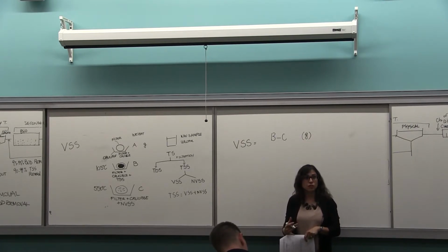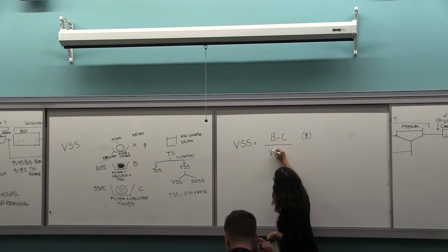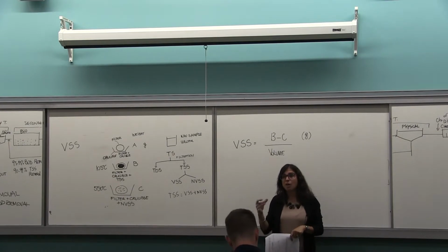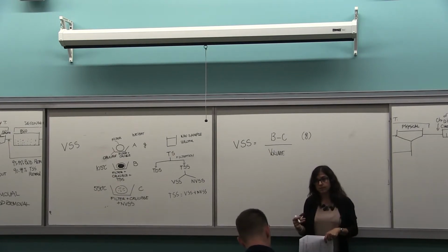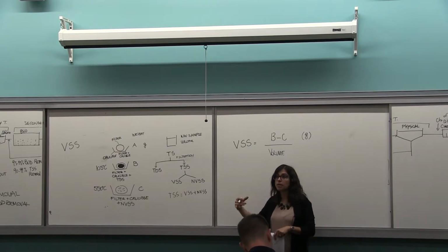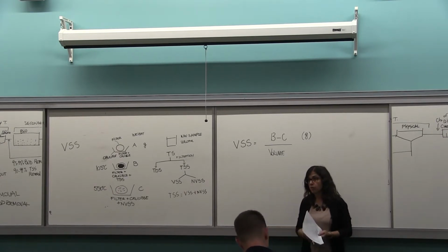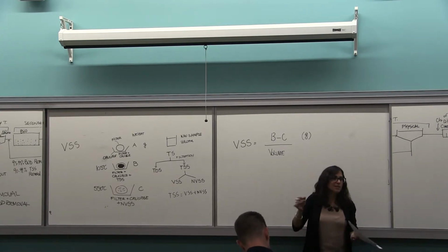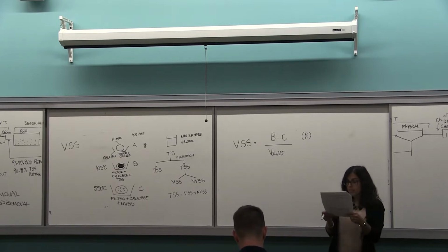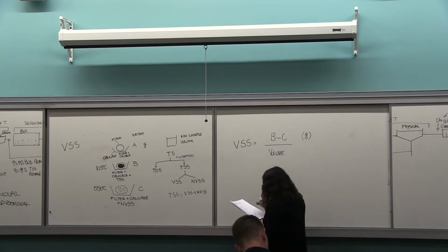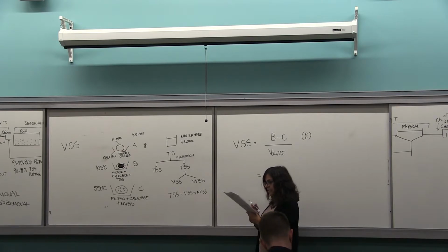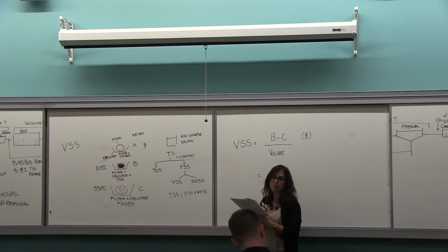VSS is a concentration. We need to consider how much we filtered at the beginning. So that will be gram or milligram per liter of wastewater. Now, here I use A, B, and C just to illustrate; all of it is written there. So for the VSS, MSS is the mass of dry crucible, filter paper, and solids.